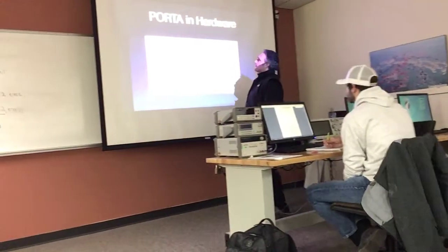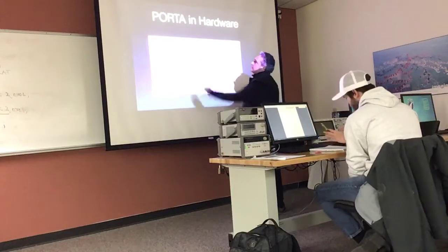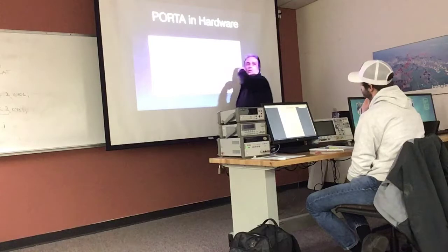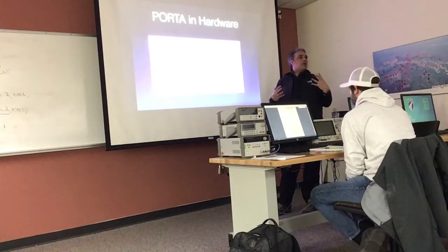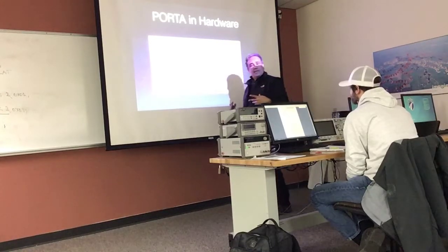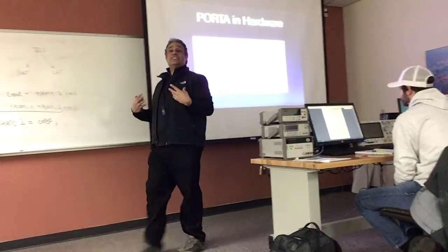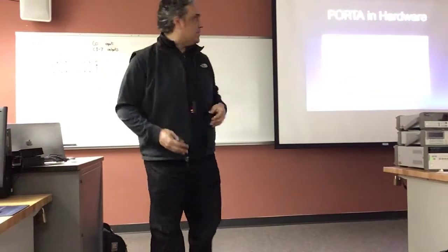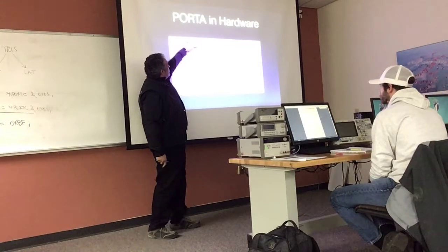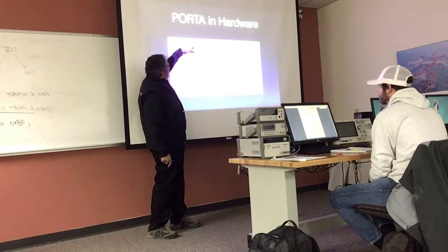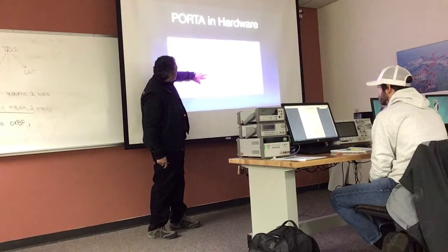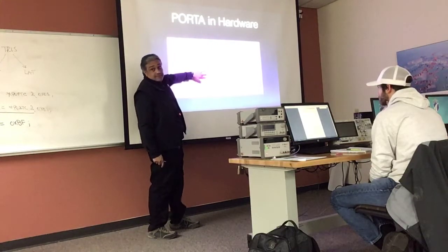All right. So here it is. Here is the pinout. In green, you see the nomenclature for digital pins in the Microchip world. So Microchip calls anything RA, RB, RC, RD, RE a digital I/O. That is the GPIO, general purpose input output. However, notice that they are not in sequence. You're going to have A0, A1, A2, 3, 4, 5, and there is 6 and 7 actually split on pins 13 and 14. See that?